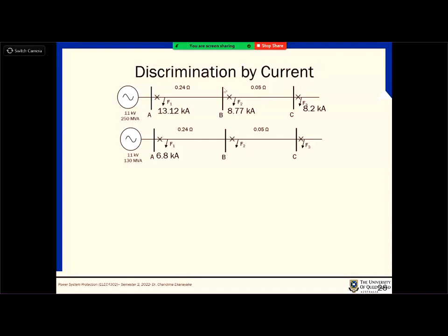So what happens, let's say, when you set your parameters of the relay based on this, and then suddenly the short circuit level of the system changes for some reason, like the number of transmission lines connected to this substation has dropped, right? But it's still capable of supplying power, but the short circuit level dropped.